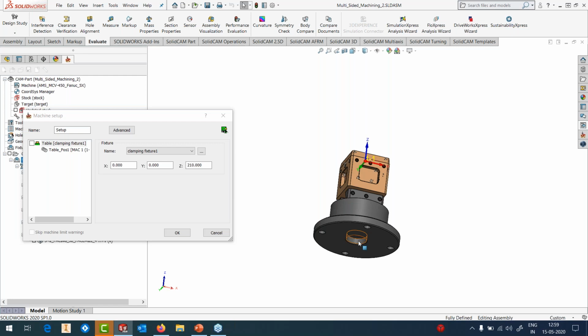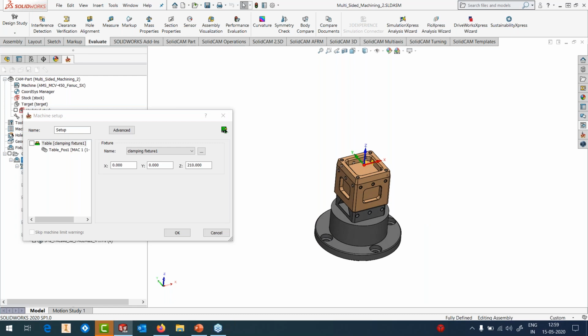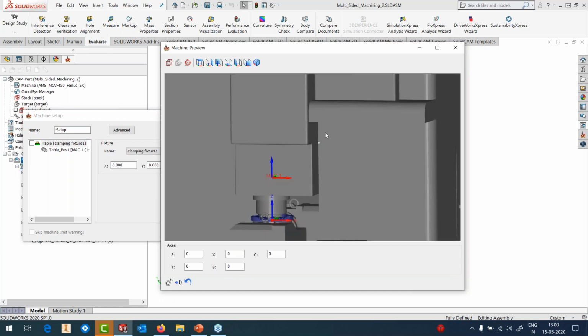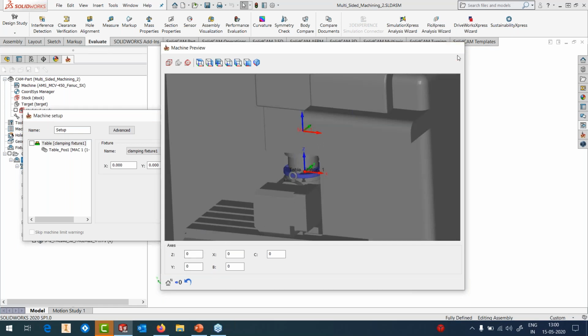Okay, so I go to the machine, I set G54.1, I mount the fixture and the part, set my G54, and I get two coordinates, XYZ, XYZ. And I do a subtraction, and I find the difference between G54 and G54.1, both in X, Y, and Z. And those values, I come back into SolidCAM and I enter here. Because remember, the controller is not going to do any kind of calculations. The calculations will happen by SolidCAM. So I bring the values, I put the values here. If you want, you can just look at where the part is going to be stationed at. Not in this case.